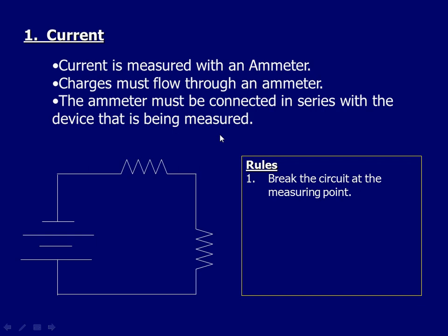The black, which is called the common, because there's only one, goes closest to the black on the power supply. So this wire didn't have to be black. It could have been a red wire. There's nothing special about the wire inside of it. I could have used a red one. I would have then followed it back to the power supply. I would have observed that this is connected to the black, and I'm going to connect that to the black. Black connects to black. Okay? All right? Next, you will connect the red to one of the reds.